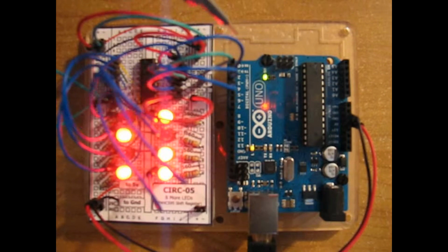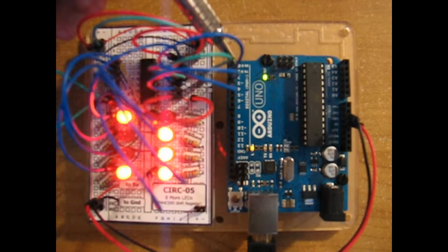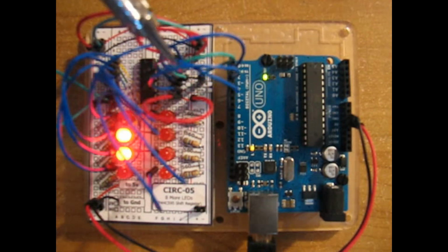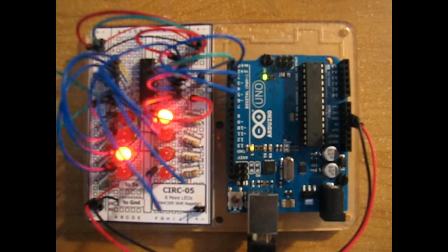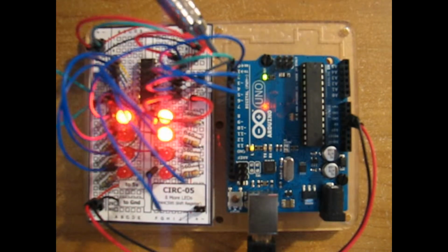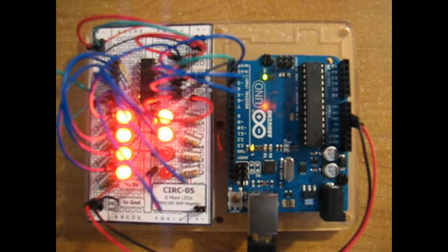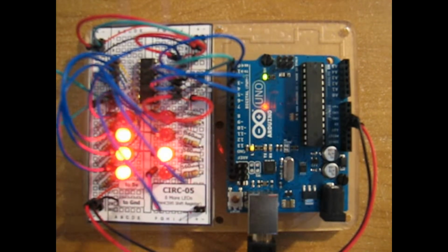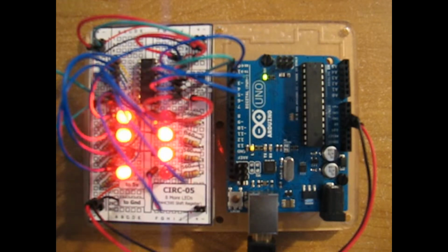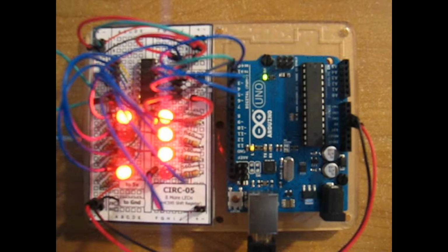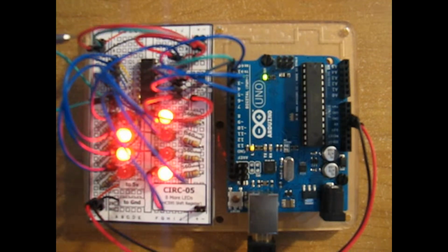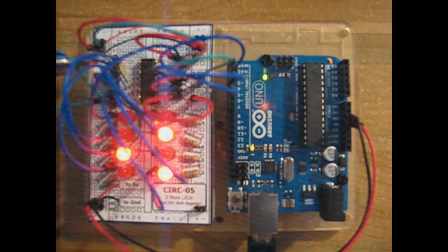And as we see here, we have the data pin, pin 14, connected to pin 2 on the Arduino. The latch pin 12 is connected to pin 4 on the Arduino, and then we have the clock set to pin 3 on the Arduino, and we'll be sending various codes to each of them to control the LED states. And then each LED is connected to Q0 through Q7, so pin 15 and pins 1 through 7.